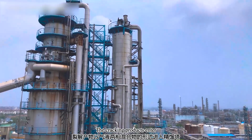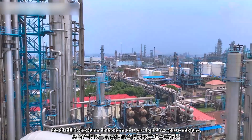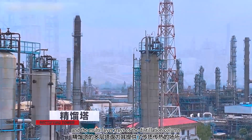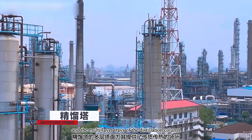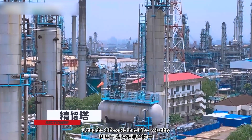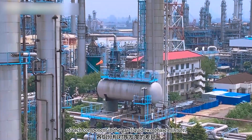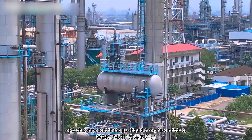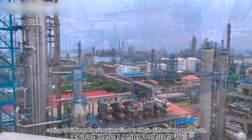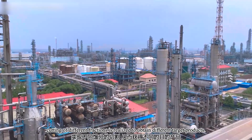The cracking products enter the distillation column in the form of a gas-liquid two-phase mixture, and the multi-layer trays of the distillation column provide a place for mass and heat transfer, using the difference in relative volatility of each component in the gas-liquid two-phase mixture. Cutting of different fractions is realized to obtain different target products.